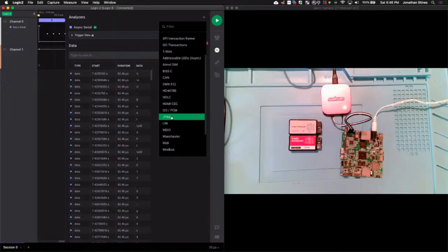If it's an Atmel, you want to use something like a PICkit. So if you're wanting to either dump or flash some firmware onto an MCU or flash memory, you would use whatever programmer is assigned to that particular chipset. Outside that, you can use a logic analyzer for some limited boundary scanning, but that's not really why it's designed, but the capability exists.